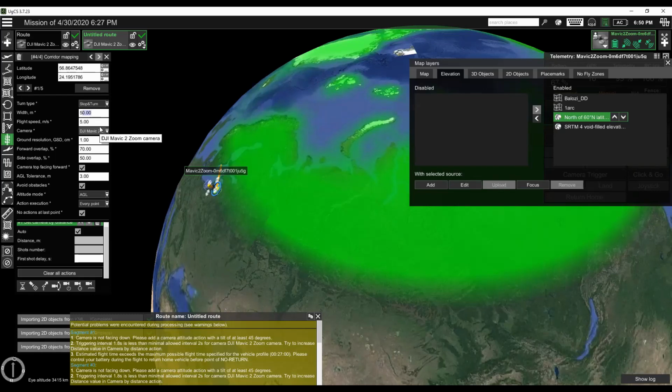It is possible to upload the next route while the drone is still in the air. Once the route is completed, the drone stays hovering at the last waypoint, and you can upload the route and continue the flight without landing. So the land tool is necessary if you definitely want the drone to land once the route is completed.